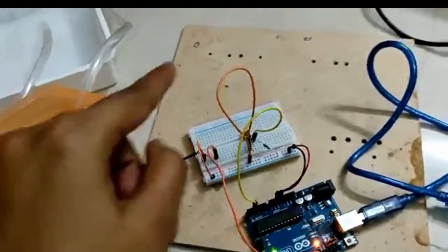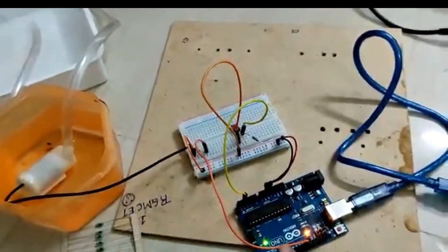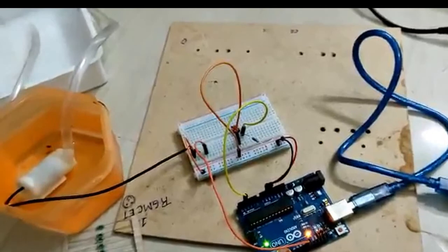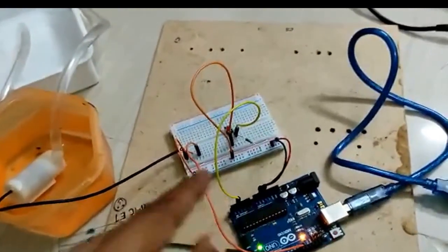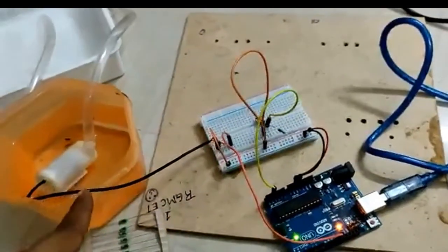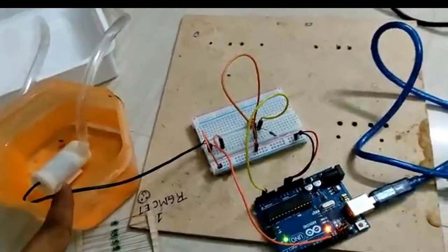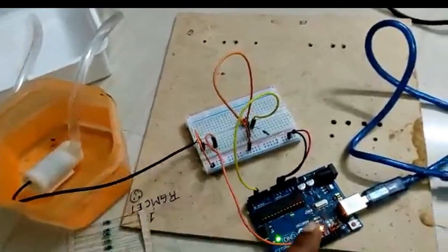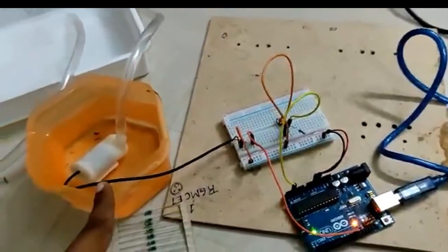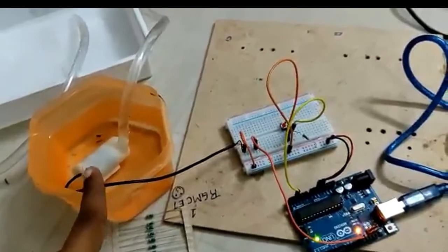Here the condition is that we set the time limit in our Arduino board through the coding. If the time limit exceeds the given time, then the control signal won't be passed to the DC motor, so even though the main power supply is in on state, the signal won't be transferred to the DC motor, and the motor will be in off state.